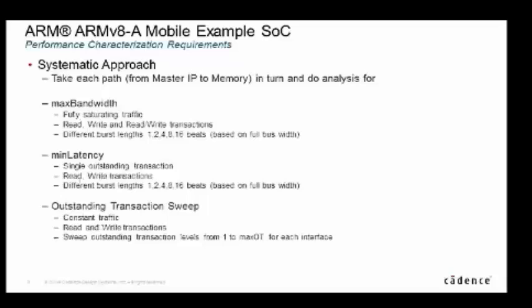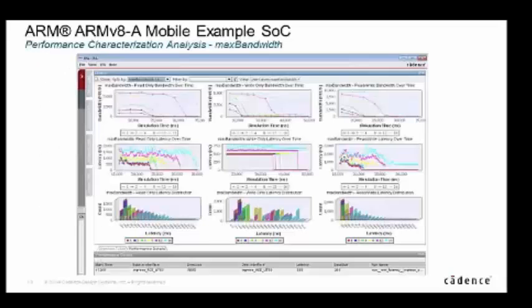So by automating the assembly of the CPU subsystem, you can automate the creation of test benches that go along with that. However, a lot of customers we have don't have IP-XACT, and so we have effectively a spreadsheet. You can, from a spreadsheet, define the black box that is your subsystem, and we'll generate a UVM test bench automatically and tests automatically for it.